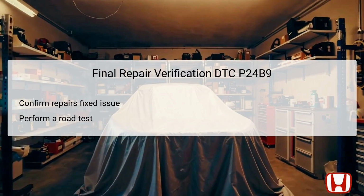During this test, the technician should monitor the vehicle's performance closely for any signs of the return of the check engine light or related symptoms. If everything operates normally without the reoccurrence of the DTC, then the vehicle can be deemed repaired. Maintaining accurate records of the diagnosis and repairs is also critical for future reference and accountability.